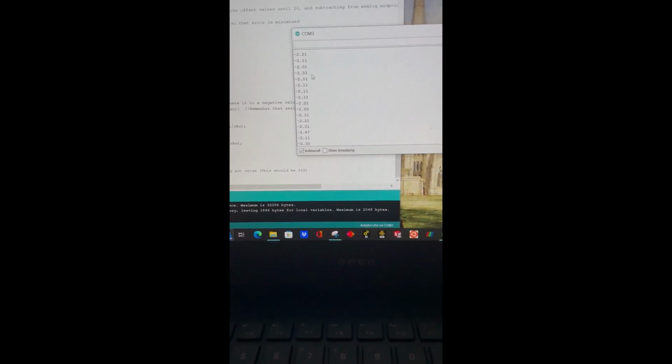So right now I've written this Arduino code, and right now I've just written it so it measures our flow velocity. In the real test, I will be actually measuring the differential pressure, so it's pretty easy to calculate from there. So right now it's showing a negative velocity because we just slightly moved that, so it messed up the calibration. But still, we will be able to get a pretty good demo from this. Let's try to get an actual plot.